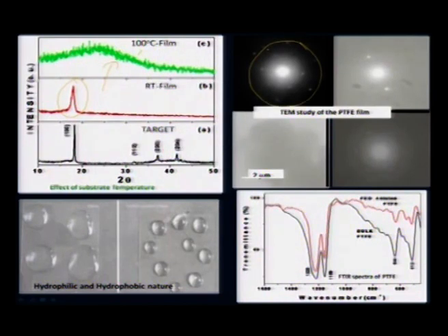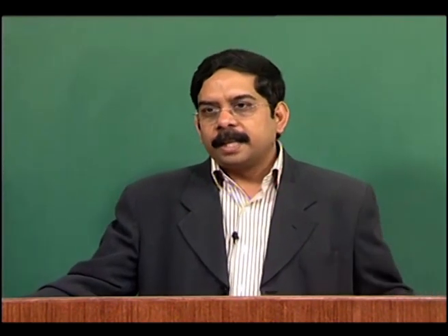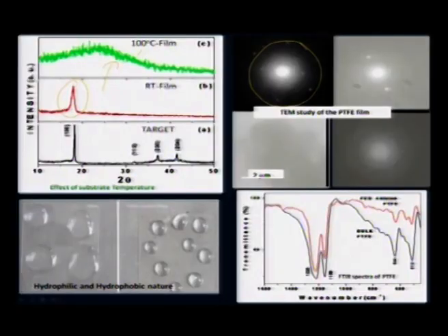You have a crystalline film pattern emerging. How do I know? Because you are controlling in nano size, it is very difficult to know whether you deposited any film or not. If you deposit on a Teflon coated glass, this is the Teflon coated glass, and this is water droplets on glass, you can clearly see that the contact angle changes in the Teflon coated glass, meaning you have made a very effective coating of Teflon on the glass.